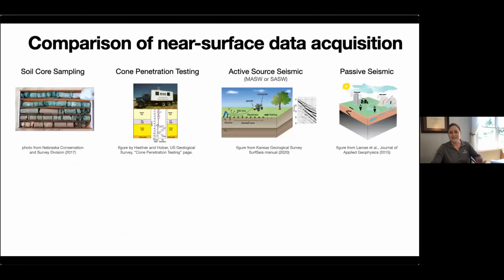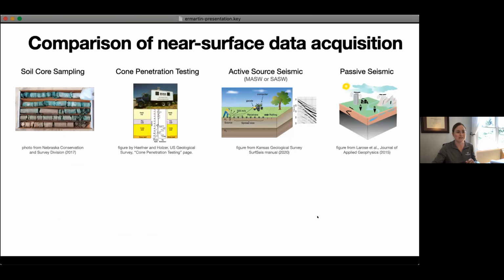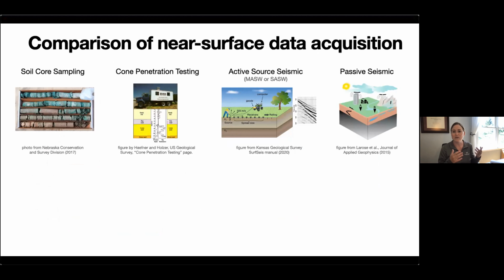In geotechnical engineering and near-surface geophysics, there has been some application of inverse problems in the past, but typically on the side of seismic imaging, where we send mechanical waves through the ground. We have an array of sensors and try to detect when certain vibrations hit which sensors, to infer the speed of those seismic waves underground.